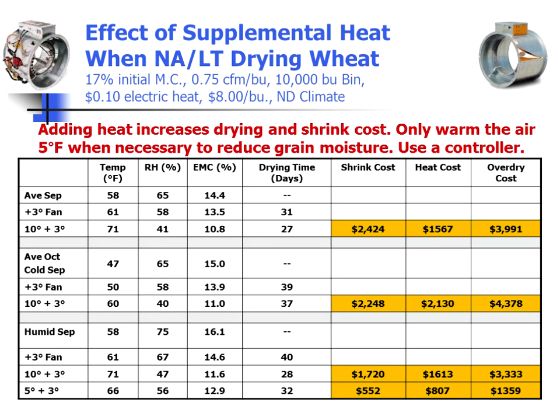Frequently, with the static pressures that we'll see working with wheat, we might see 4 or even 5 degrees of temperature rise. And so in September, even though the average conditions don't quite get us to the 13% or 13.5%